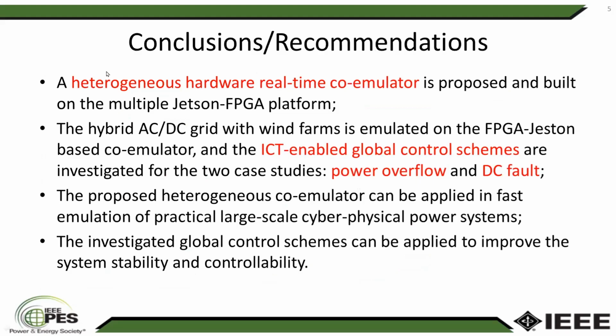To conclude this work, a heterogeneous hardware real-time co-emulator is proposed and built on multiple Jetson FPGA platforms. The hybrid AC-DC grid with wind farms is emulated on the FPGA Jetson-based co-emulator, and the communication-enabled global control schemes are investigated for two case studies: power overflow and DC fault.